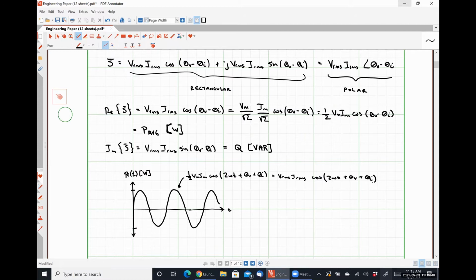In an electric machine, the reactive power is what's used to create and maintain the magnetic flux needed for rotation, right? So in a motor, particularly an electric motor, it's got a rotating magnet called a rotor and a stationary magnet called a stator. And it spins around in either a clockwise or counterclockwise direction, depending on the phase sequence of the motor, if we're talking about three-phase stuff. Well, as the rotor spins into phase with the correct part of the stator, that causes the output voltage to be higher, which generates more magnetic flux, which keeps the machine going.